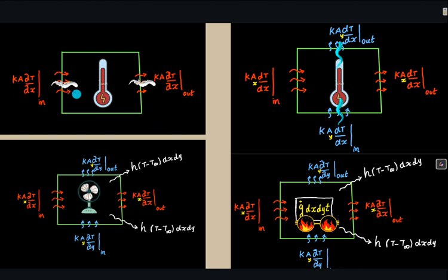Okay, so greater the difference between the temperature with respect to x-axis, in this particular case, greater is going to be the heat that is going to rush from the left extreme end towards the right. All right, so this is going to be the expression for heat that is coming in, and there is a proportionality constant, which is K, which is called the thermal conductivity of the particular material. And you can see that the thermal conductivity depends on the material, so it changes from one material to the other.